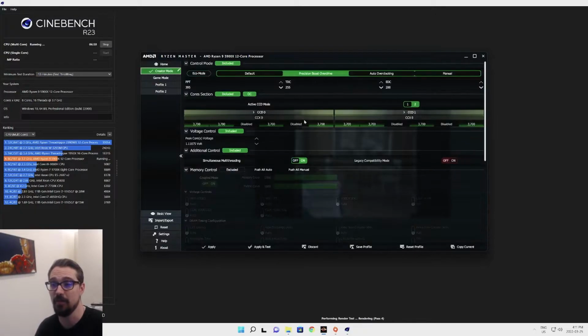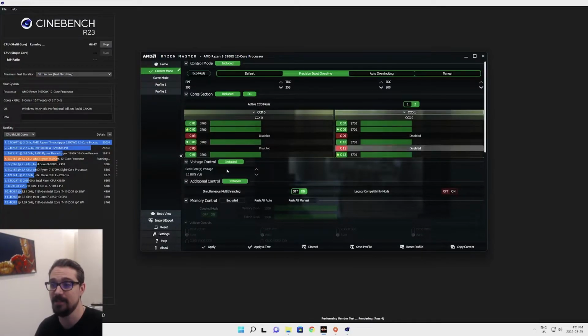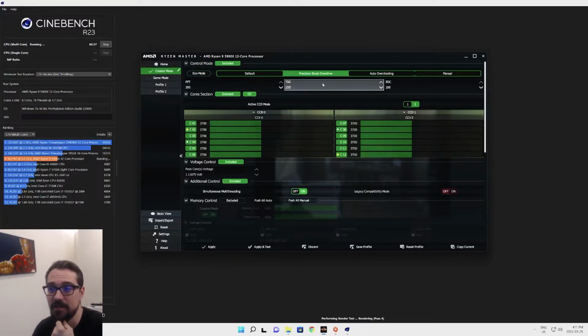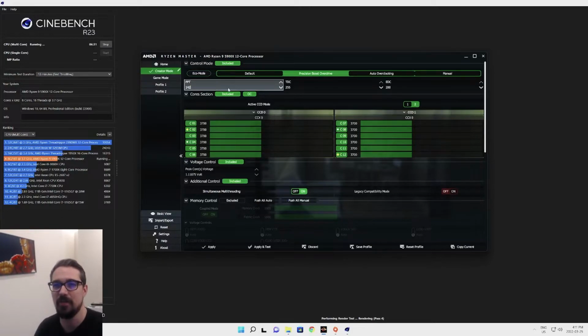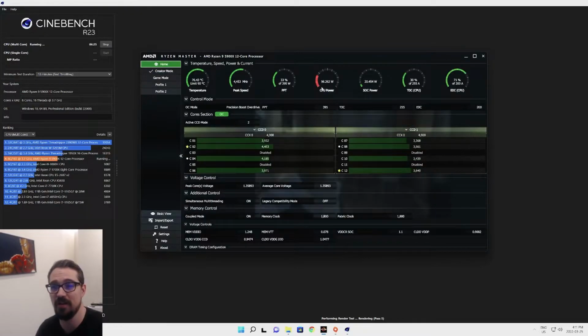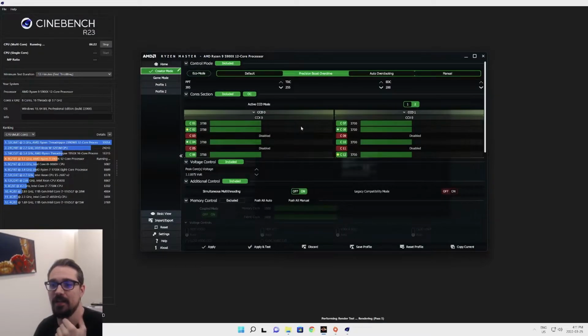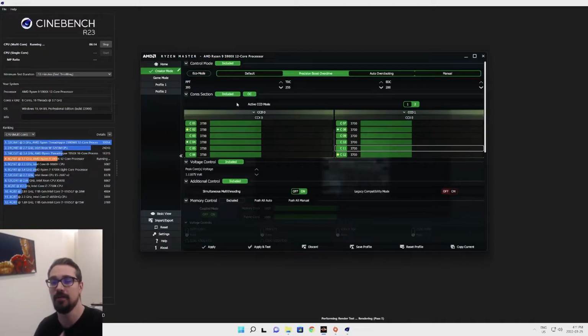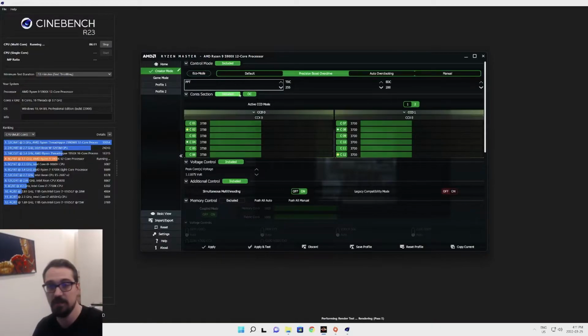So if we go back into creator mode, we can go back to our CCDs and re-enable those cores. Probably going to require another reboot. And then we can actually talk about our PPT, our TDC, and our EDC. Now, if our stock PPT was 142, I would recommend looking at which ones are being throttled. Again, in your home screen, you can see which ones are throttling when you're at a full load, and increase them incrementally. I don't recommend necessarily just going to the maximum power limits for the motherboard unless you've got the cooling for that. But if your stock is 142, you could say, well, let's go to 185.